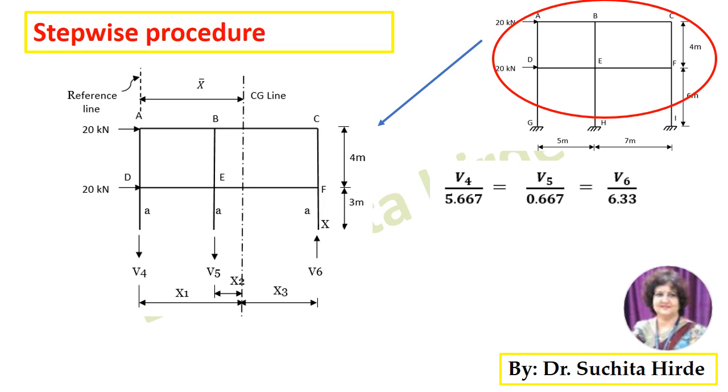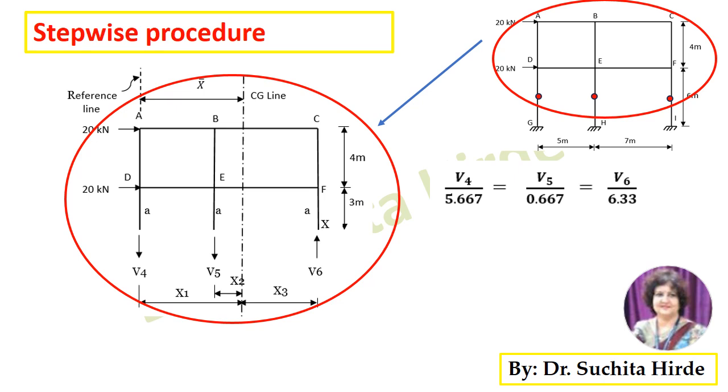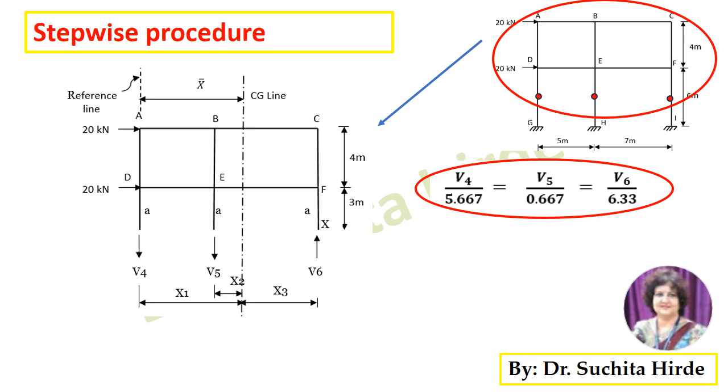In the same way, we have to derive the equation of axial forces for the bottom story. For that, we have to consider the hinges at the center of the column of the bottom story, draw the sketch up to the hinges, show the forces, and derive the equation. So we get a similar equation because the position of the CG line is the same.